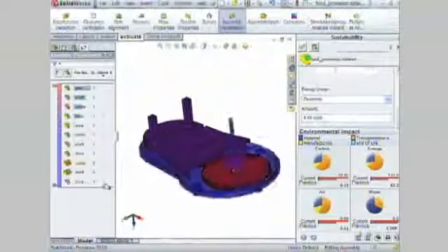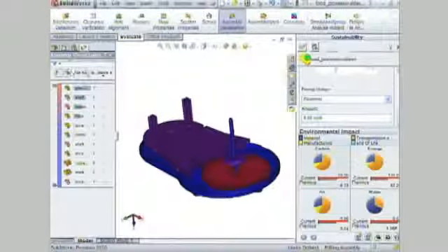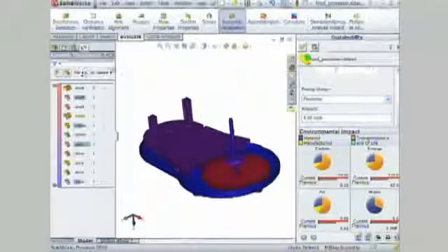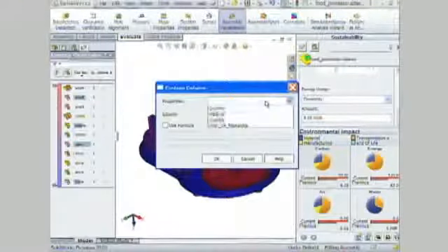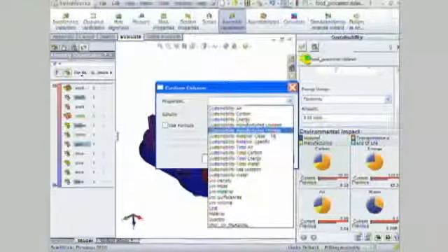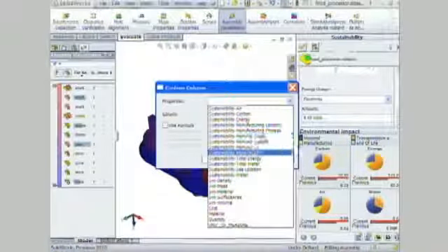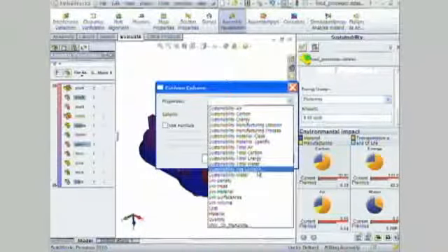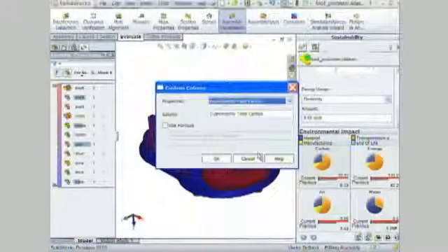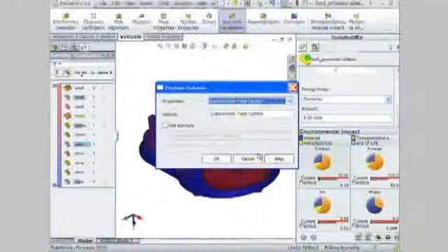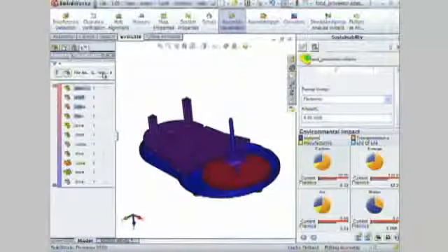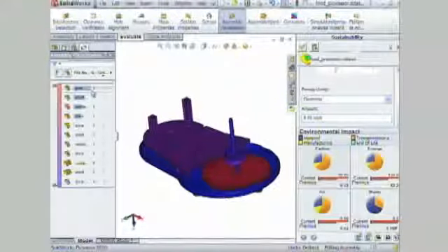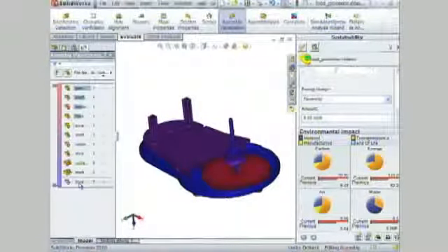So why is this important to sustainability? Well, we can actually expose not only standard properties, but the environmental impacts that we calculate in SolidWorks Sustainability. So I can do things like say, you know what, I want to look at the total carbon footprint for each of the components inside of my assembly. So when I do that, I will again sort, and I can see my components listed from those with the highest carbon footprint down to those with the smallest carbon footprint.